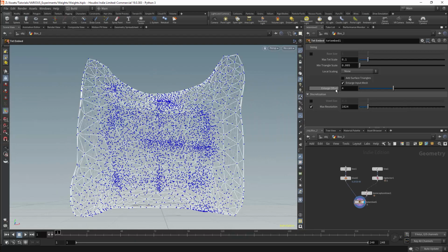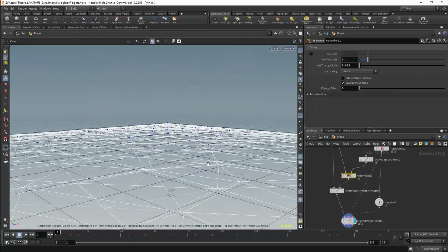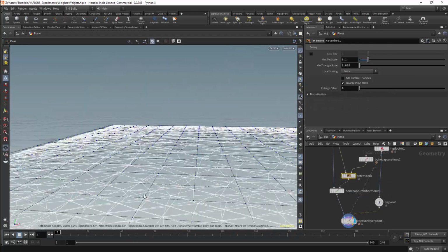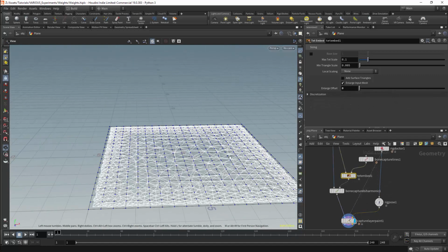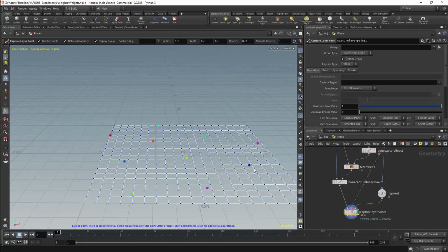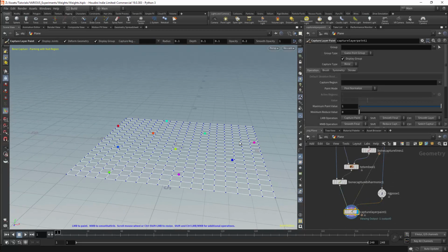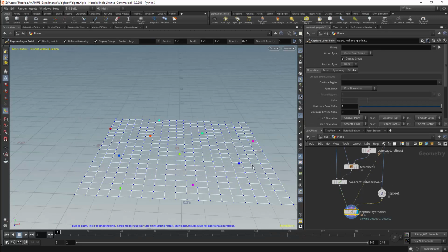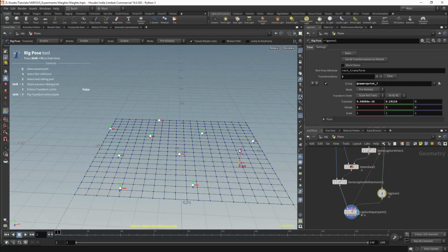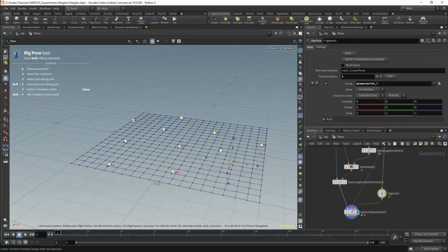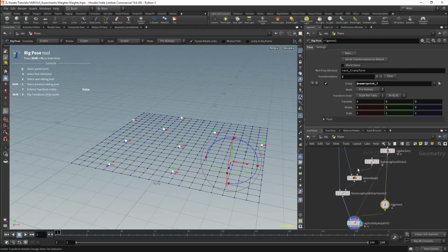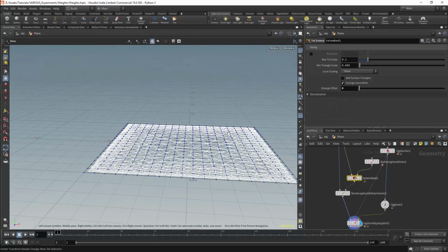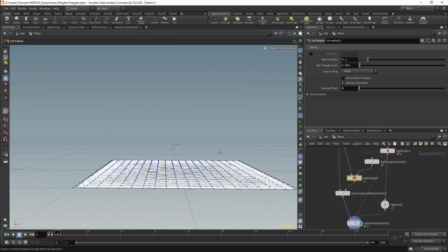There is one more case which we should look at where it is beneficial to know how to approach weighting. In this example, the weighting will also fail. I've weighted the flat geometry with points that have been scattered along its surface. If we move these joints, however, they will have no influence on the mesh. This is another case where the enlarged mesh is important, and that is dealing with sections of a mesh or flat surfaces that have joints directly affecting the surface.